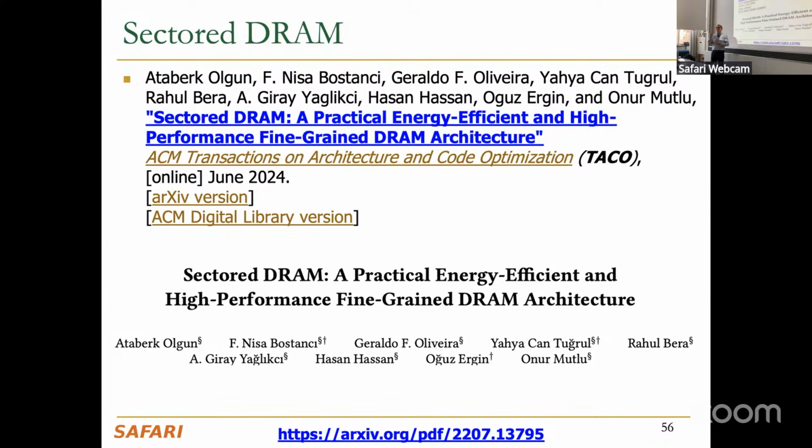So if you want to get only one bit, you're really activating the entire 64 kilobyte row, assuming it's 64 kilobytes. Basically, you're really accessing 64K minus 1 bits for no reason, assuming you don't have a very good locality, let's say, even you don't have any locality. Right? So that's the problem that these fine-grained DRAM architectures are trying to solve. How do I activate as little as possible in DRAM that matches my locality characteristics? Right?